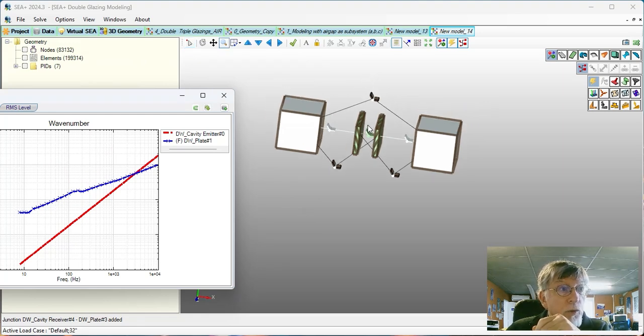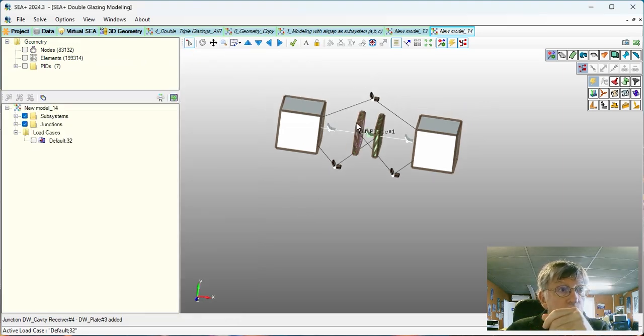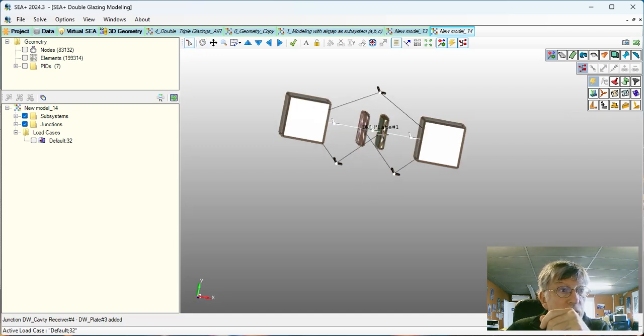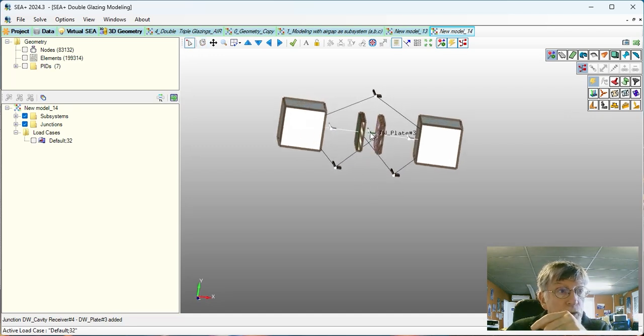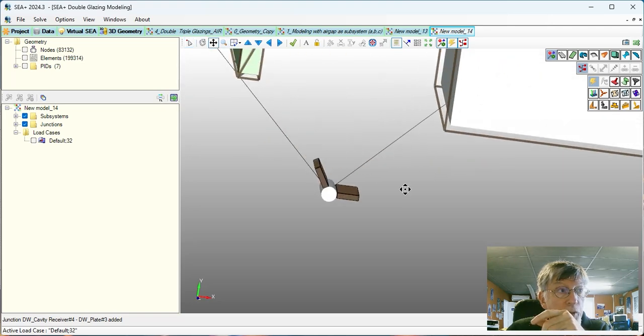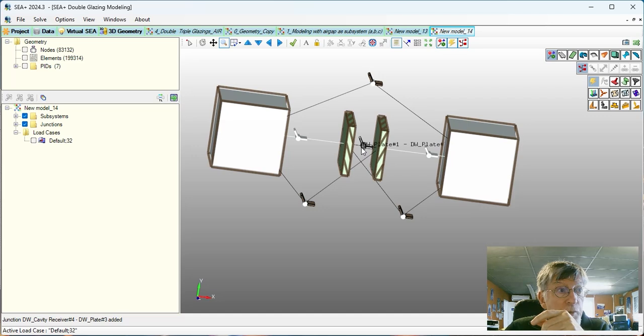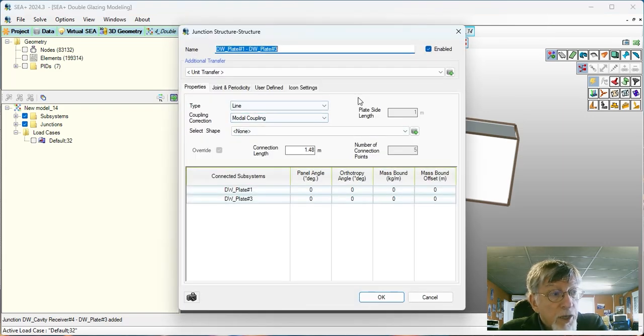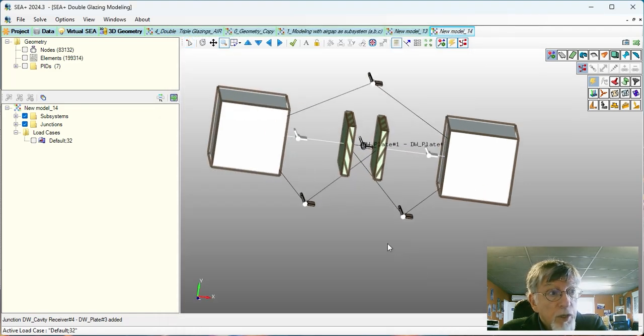And so the panel modes are then radiated into the second panel through this, which is a mechanical coupling loss factor, because we assume these two plates are maintained by a frame, a metallic frame, a small one, and this metallic frame induces line coupling on the panel, which is per default equal to the largest dimension, but it's something that has to be set up correctly.